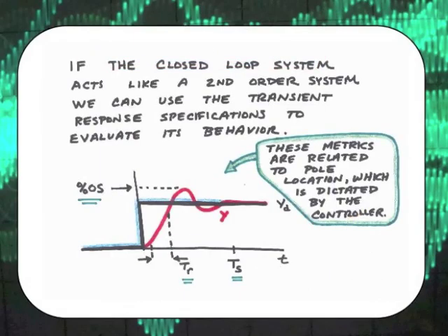So you've now seen how the transient response of a system can be tailored via feedback control, how we can achieve a desired percent overshoot, rise time, and settling time, and how we can think about the design process from the point of view of locating the closed-loop poles.